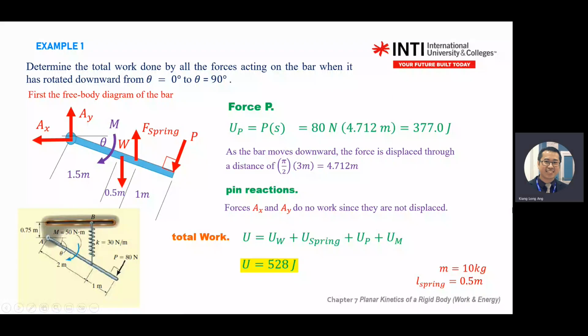Last week, we stopped at what is work. Again, some forces do not create work. Just need to be careful. Some of the forces do not do work. And for a rigid body, you need to pay attention to moment. Moment will do work: moment multiplied by the angle traveled. That one is in radians, not degrees.